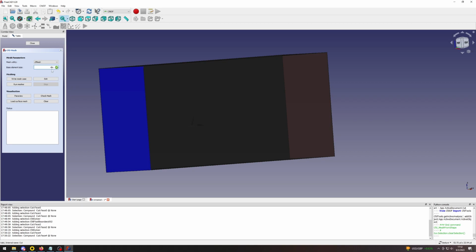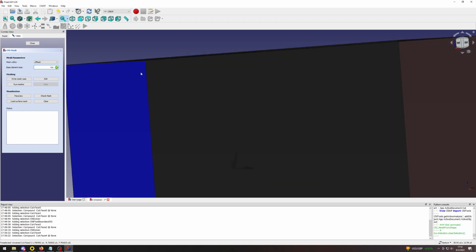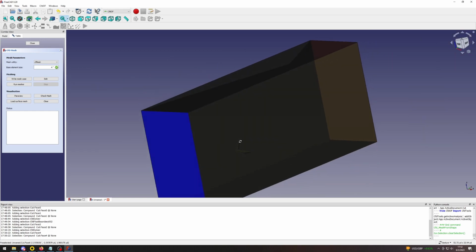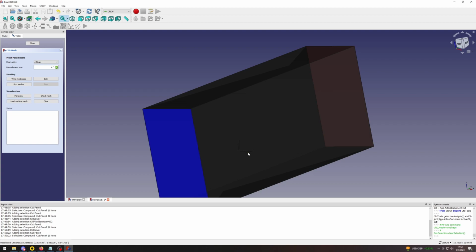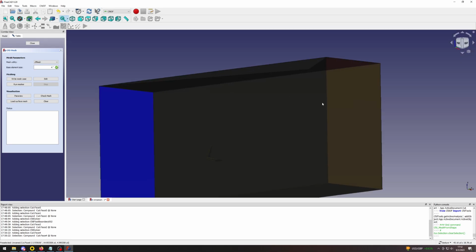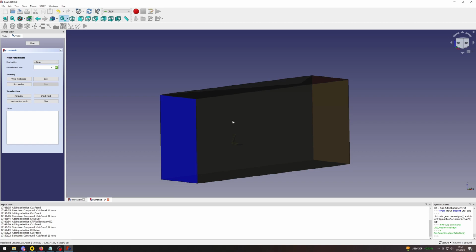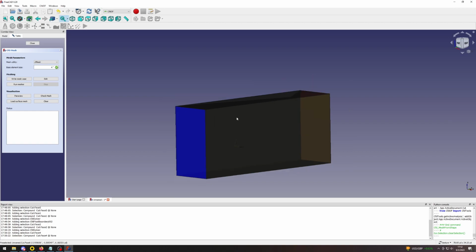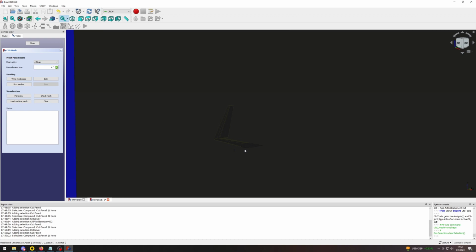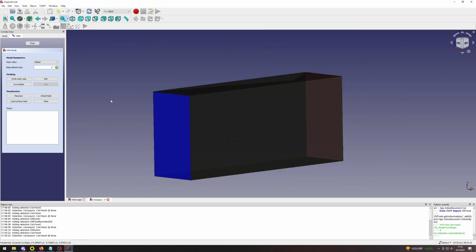Anyways, we're going to put 4 inches on our base element size here. This is just the basic mesh. So we're going to calculate things that are 4 inches apart. That is terrible for a wing of this size. I don't even remember how big it is, but just at a glance from the section of it that I have in my room, it's roughly 6 feet long, this little section here. But remember, we're modeling this huge area. So this is where the idea of a region refinement comes in. We're going to do a basic, very rough calculation of everything, but as we get closer to the wing, we're going to make the mesh more detailed. So there we go. We have our base element size of 4, and that looks good.